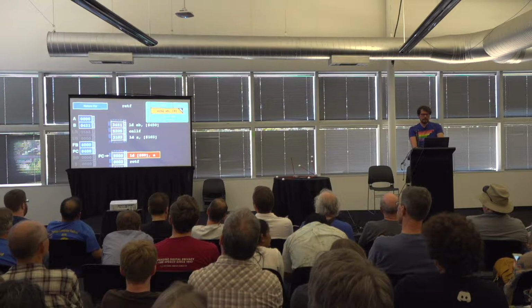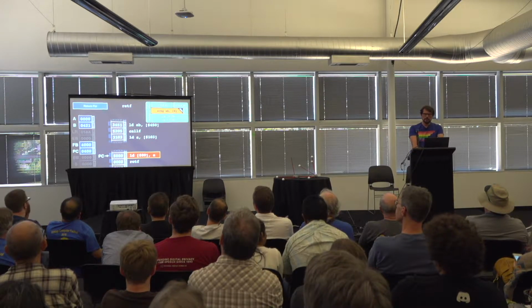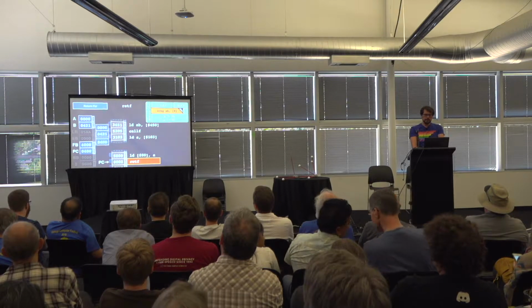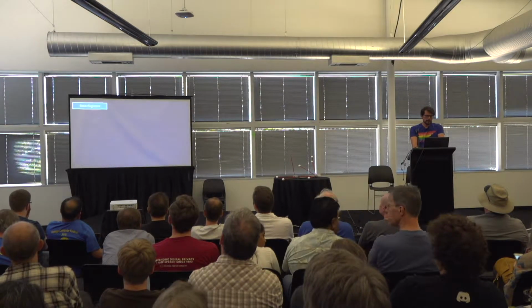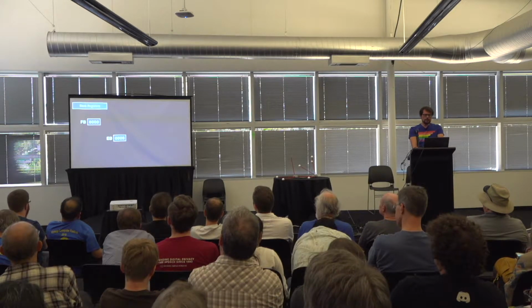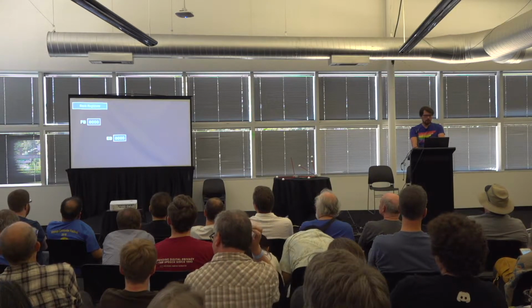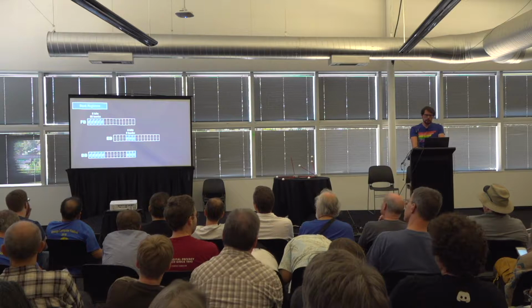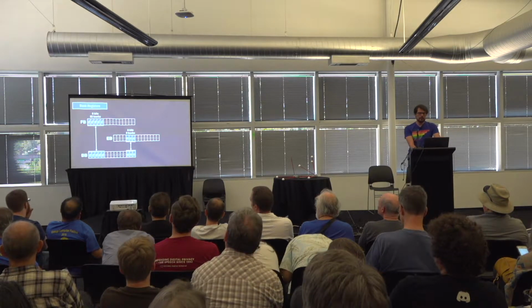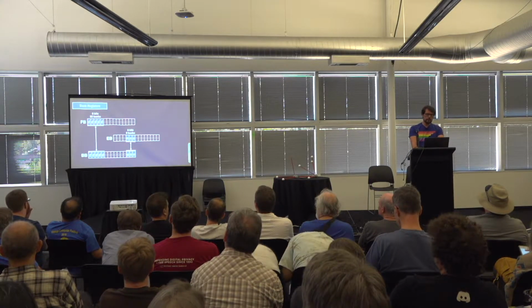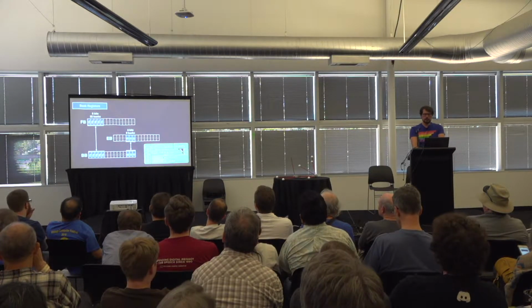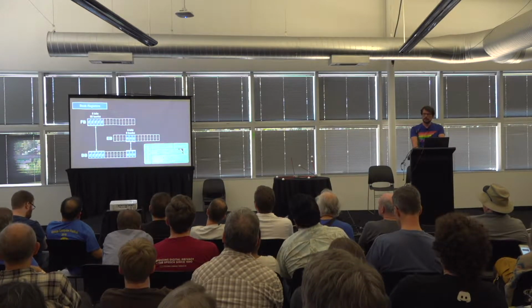The exact same exchange AB, indirect for instruction can be used for a far return. It moves the original values back into FB and PC. The two bank registers only hold 5 and 3 bits respectively. The other bits are 0. There's a third bank register, BB, both banks, which mirrors the information from both other bank registers. The call far both banks synonym is a double word exchange instruction that updates the program counter and both banks.